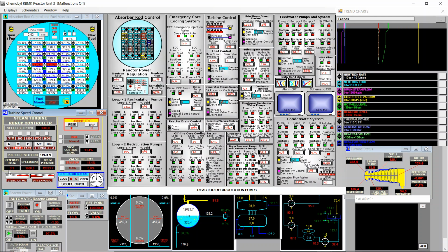And we see generated load 3%. And now I will increase reactor power for one reason. If the power from the main steam line is not enough to have a generated load higher than 0, because there is friction, there is turbulence in the flow, etc., it can happen that the generator draws electricity from the grid, and if this happens for an extended period of time, then a turbine trip will be triggered.